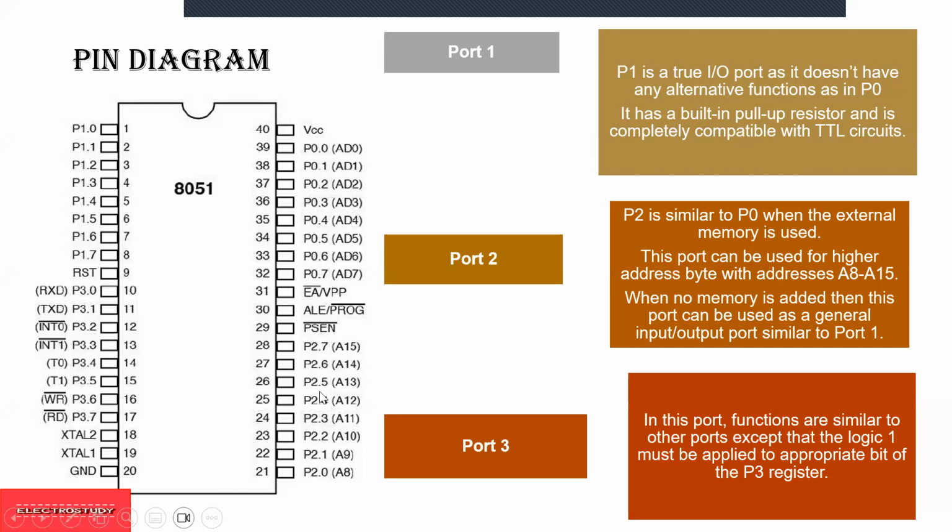When looking at port 0, what happens is, when external memory is used, the lower address bytes will be applied on it; otherwise all the bits of this port will be configured as input or output.